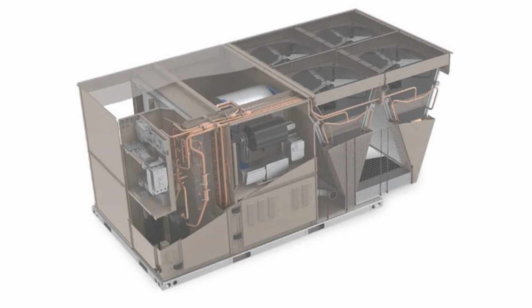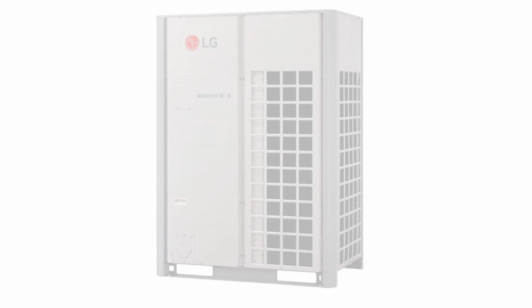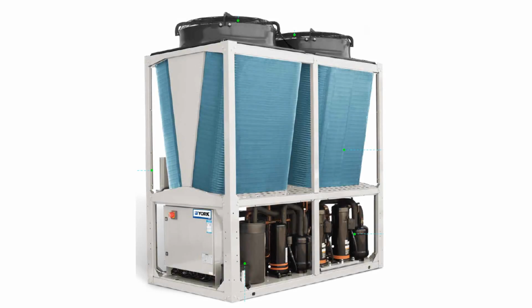The 3 types from which will be selected are a direct expansion rooftop unit, or RTU, a variable refrigerant flow unit, or VRF, and a water-to-air heat exchange chiller. Each of these systems is a heat pump unit, meaning that they use reverse refrigerant flow to create heat, as opposed to burning fossil fuels. This is a good way to keep ASHRAE decarbonization incentives in mind as the team works on their design.